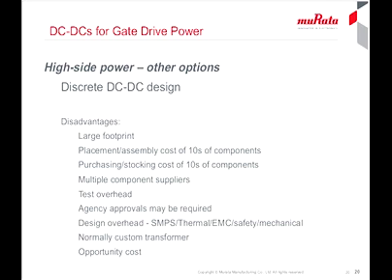Some users like the security of knowing a discrete design can be assembled from multiple vendors of components, but the transformer design will inevitably be non-standard and often have to be outsourced. A module can be a quick, high-performance and secure solution. Even cost may be favorable when all overheads are taken into account. Murata Power even has a range of multi-channel gate drive DC-DC converters that can power up to 3 high-side and 3 low-side switches simultaneously, potentially saving the cost of multiple converters.